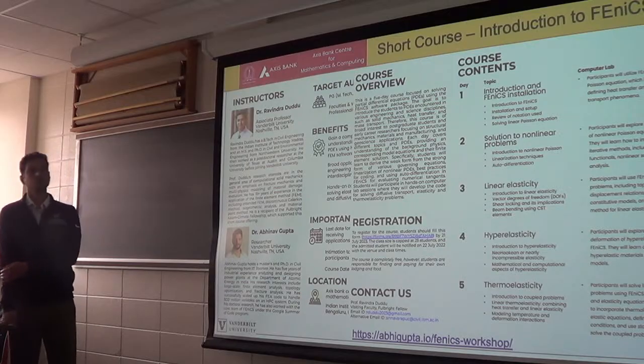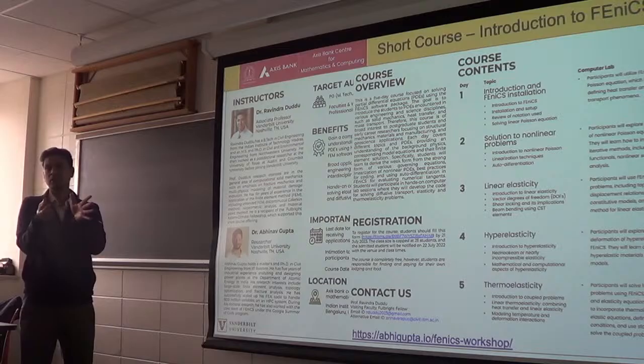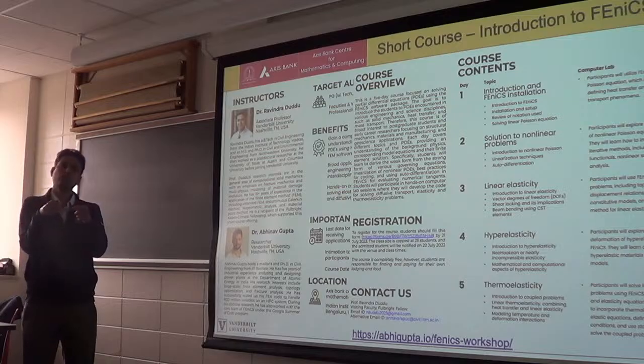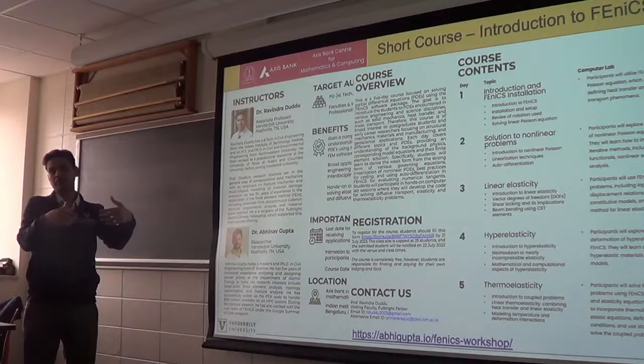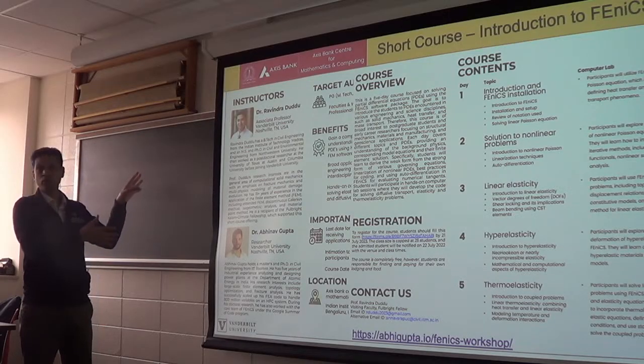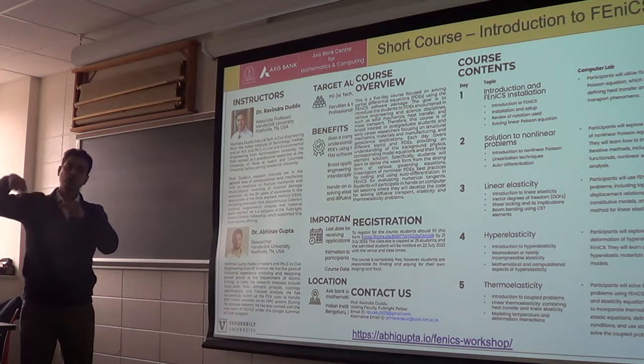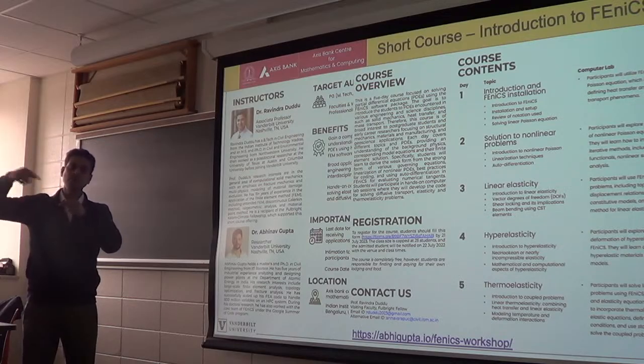Yeah. So the length scale is 5 meters, or 10 meters in some of the simulations. That means your mesh size has to be 1/4 the length scale in the region where the crack is propagating. So we have this adaptive framework where, as the fracture is propagating, we resolve the crack tip and the elements around it, and we refine it.